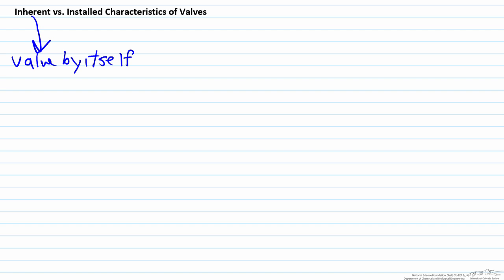And the important part about this, in terms of the valve equation, is that delta P is a constant, regardless of the amount of flow going through your control valve. This would really represent buying it off the shelf and just running the valve.